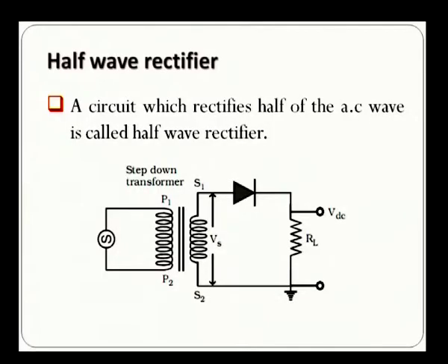And this direct current is the flow of charges in one direction, the average flow when we take over a period of time. So, an alternating current can be converted into a direct current by using a rectifier. Because the diode has the property to conduct current in one direction, that property could be used for the rectification purpose. Let us see what are the types of rectifier circuits. There are two types. One is the half wave rectifier, the other one is the full wave rectifier.